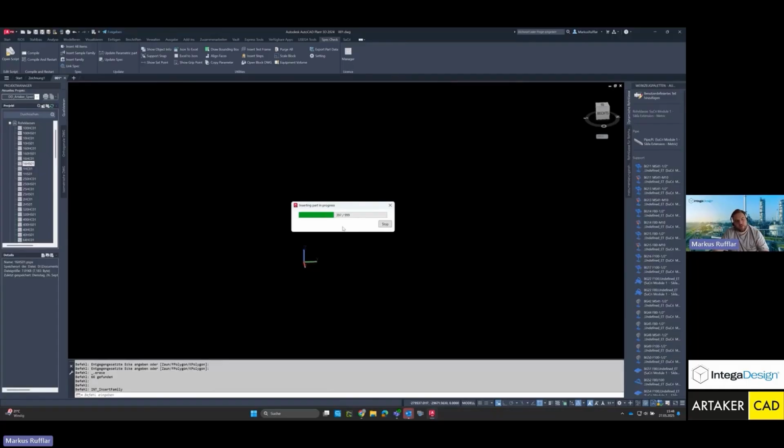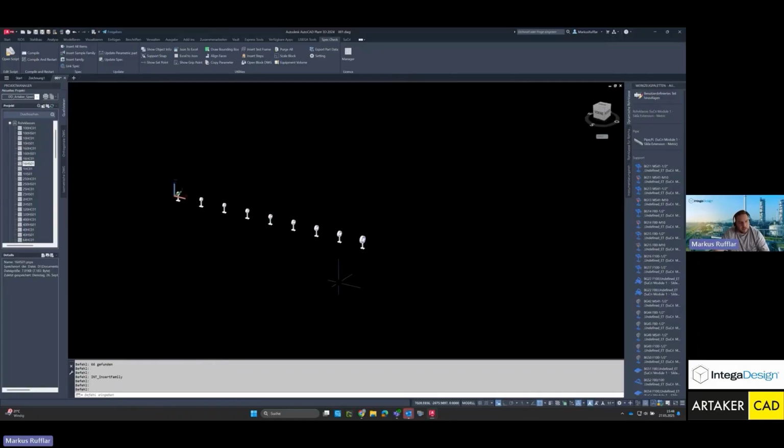So what this function ultimately accomplishes is a comprehensive Excel export of all the various properties of my numerous components within my established pipe class, plus some additional highly relevant properties. The standard properties, you can also retrieve those with the data manager or however you like. But let's say you also have custom, user-defined properties stored in the pipe class, then all of those will be exported here as well.